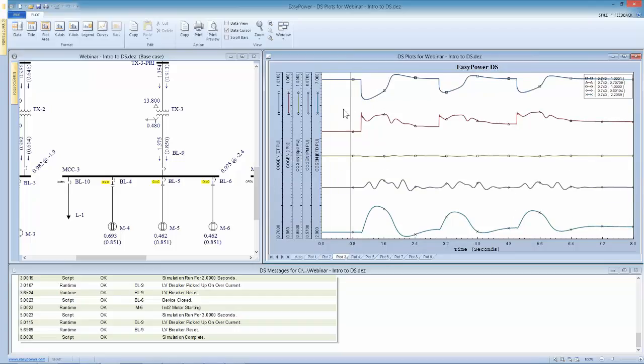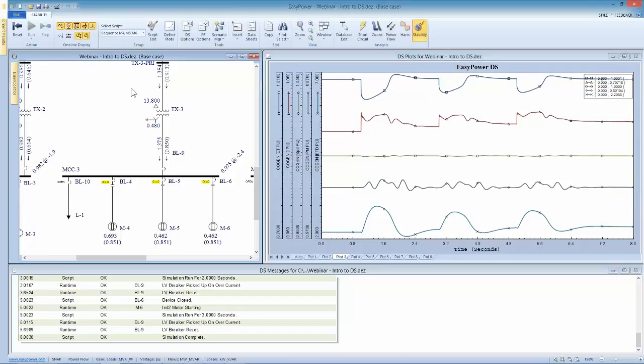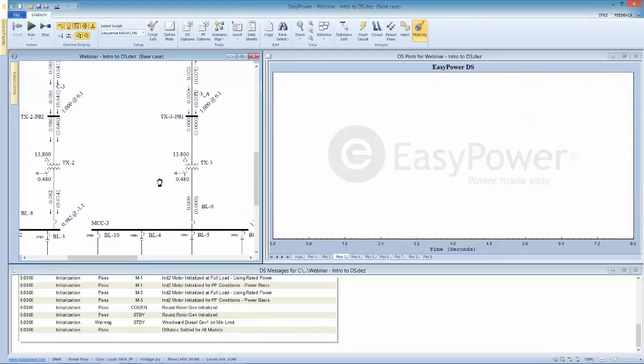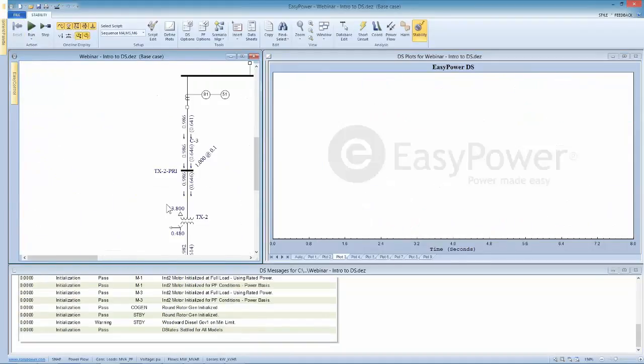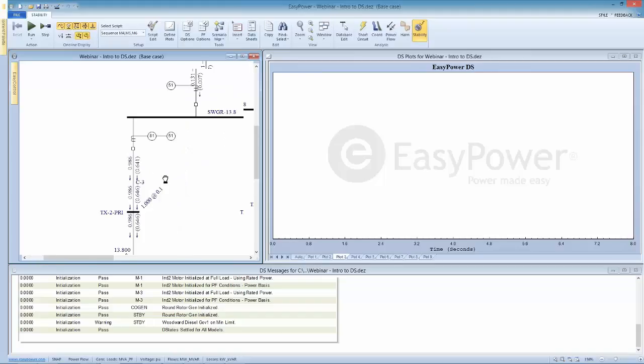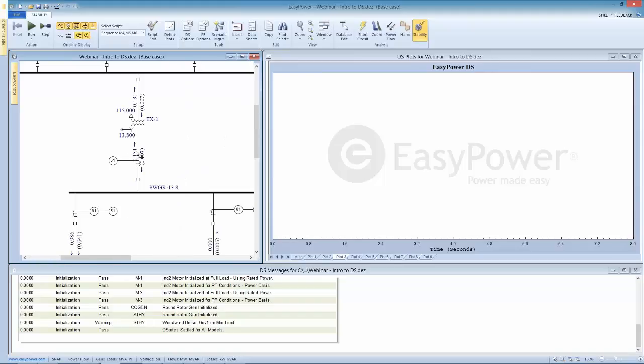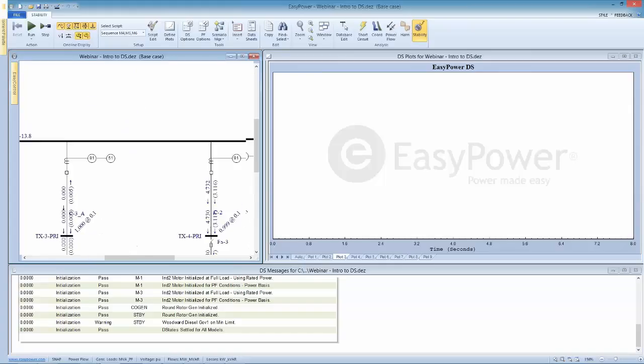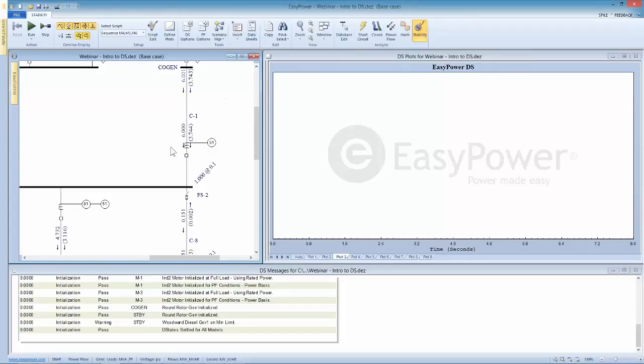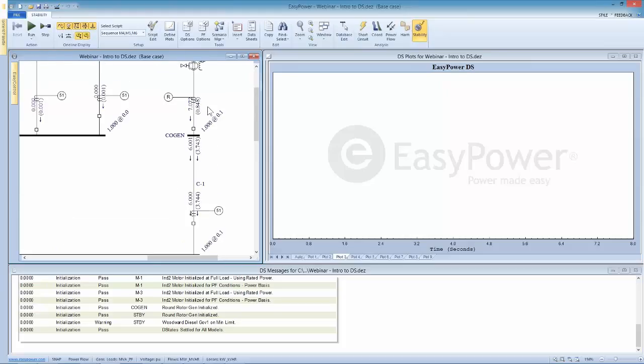Let's plot, we're looking at the cogeneration response to these motors coming online. We didn't point out earlier, but I'll get back to it in a second. The system initially starts out at a neutral position as far as the data, the power coming from the utility. So we're pretty much at a null point between the power the utility's drawn, and we come back here and we look at the cogeneration connection point, it's generating about 6 megawatts.